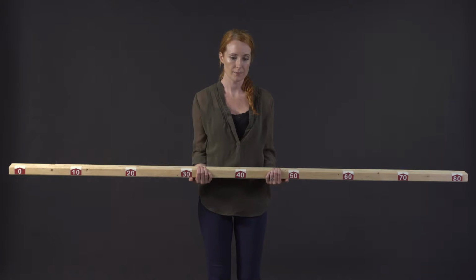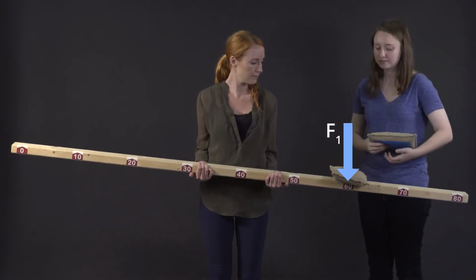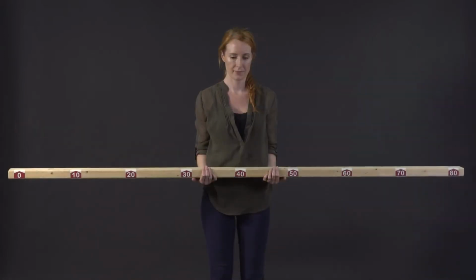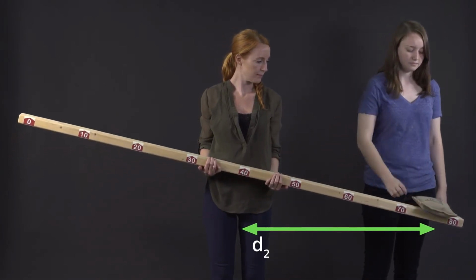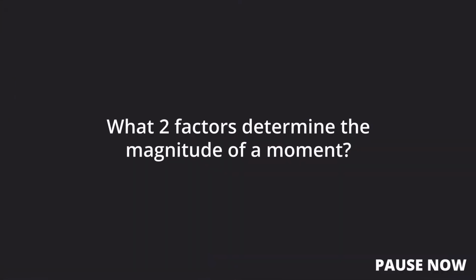To answer this question, let's consider a beam supported by two hands near its center. If we place a weight on the right side, it causes this beam to rotate clockwise. Adding a second weight increases the moment that is generated. In addition, if we move a weight from one location to another that is further away from the supports, a greater moment is generated. Now, can you state what two factors determine the magnitude of a moment? The answer is force and distance.